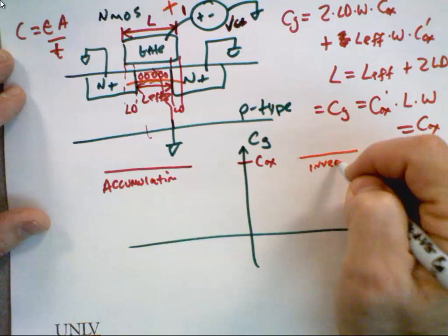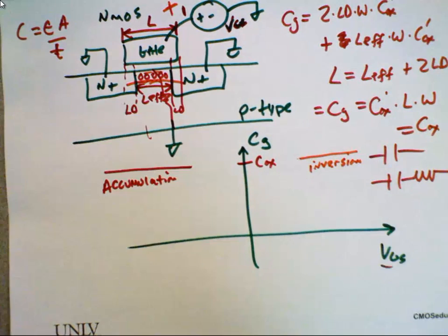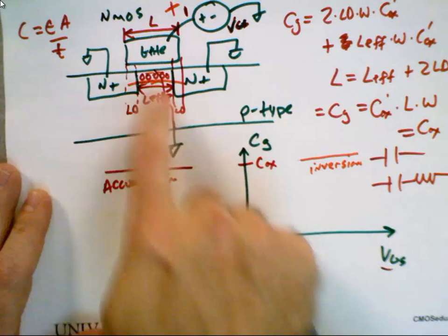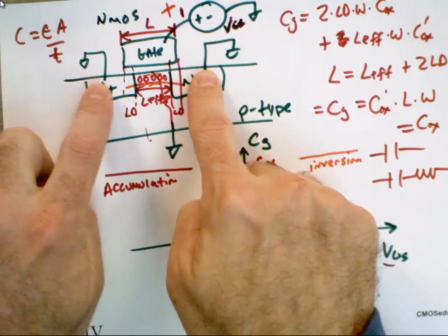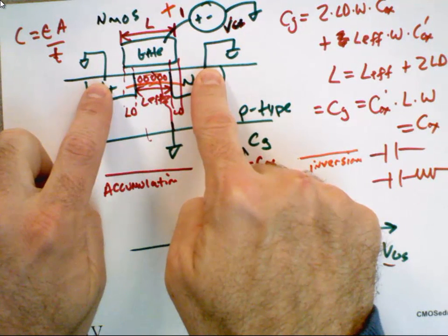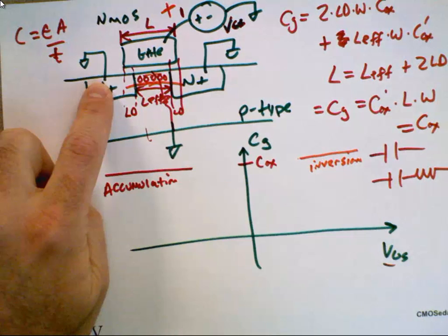So here's a good interview question. Tell me qualitatively, what does strong inversion mean? Yeah, it just means we're changing that from p-type to n-type. So here's another question. We're inverting it, going from p-type to n-type. Do you have to have current flowing between the drain and the source for the device to be in strong inversion? No. Here's a more tricky question.